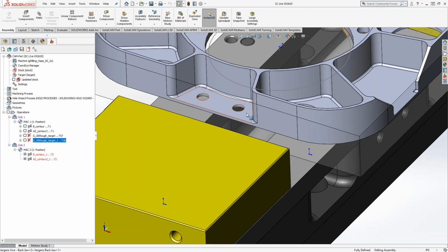And that goes back to that example of maybe you have an extended length tool or a stubby tool. You could do your 3D iMachining with a standard length tool. And then if you have deeper areas where the same diameter tool is required, but you need something a little longer, then you can set it up so that you add it in a multi-tool. It actually has the exact same diameter, but because it's an extended length tool, it can go deeper into the part because the 3D recognition is recognizing that there's more material that the previous tool cannot reach.